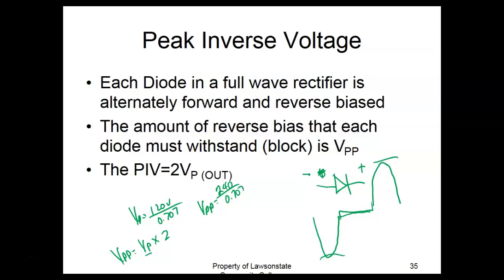So this is the PIV, the peak inverse voltage. This is how much voltage the diode can block when it's reverse biasing before it breaks over. So if you exceed this breakover voltage, that's like a 2x4. If you lay it on the table and you start putting weights on the outside of it, it's going to break over sooner or later. And when that 2x4 breaks, because you've exceeded the weight that it can hold horizontally, then it's no good anymore.